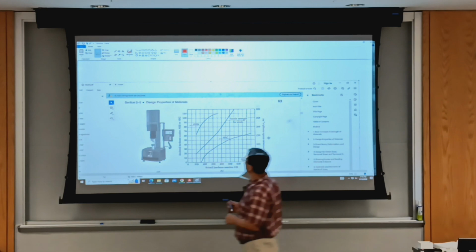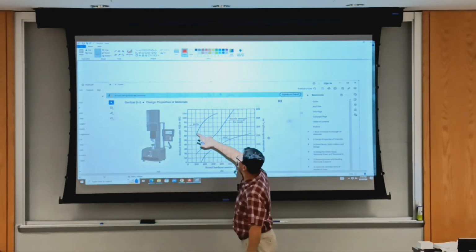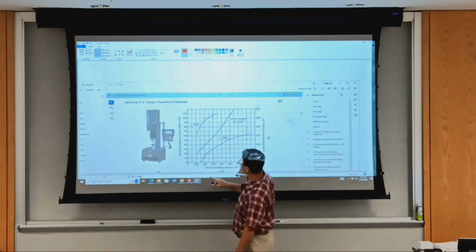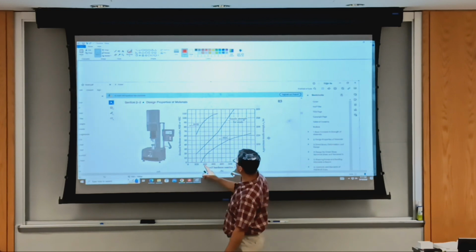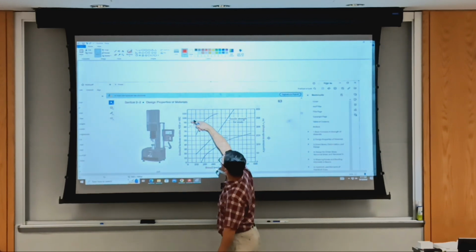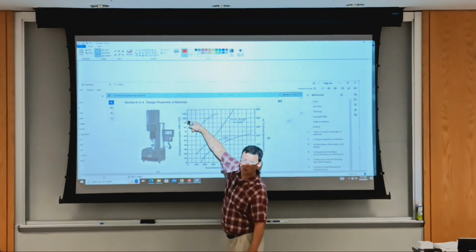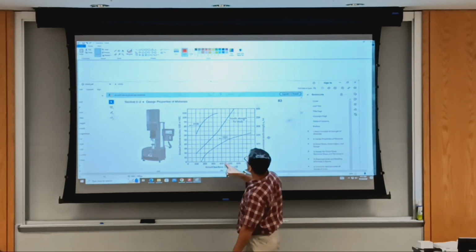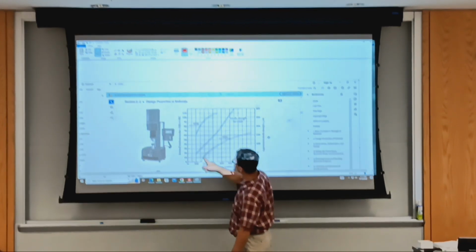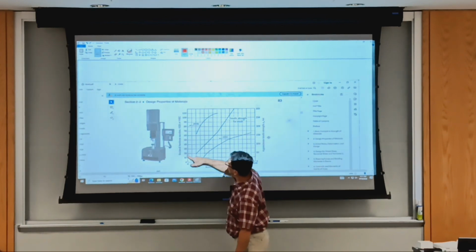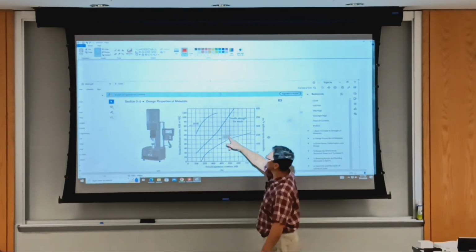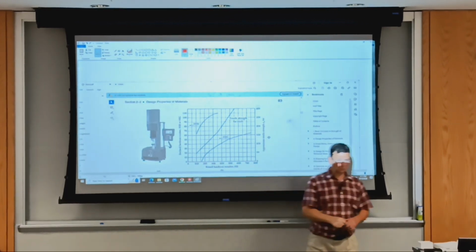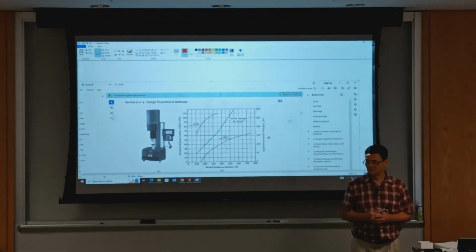So if I want to convert from the Brinell test to the Rockwell B test, I measure a Brinell number of 200 and then read the corresponding Rockwell test. See, it's a non-linear relationship between the tests. If I have a Rockwell C test, 200 moves, so it will be about 15 points of Rockwell hardness C, which is equal to about 93 Rockwell B. Does it make sense? You don't follow.